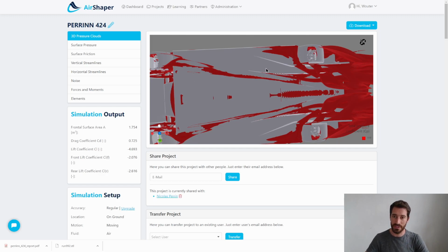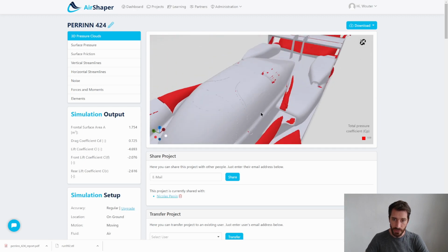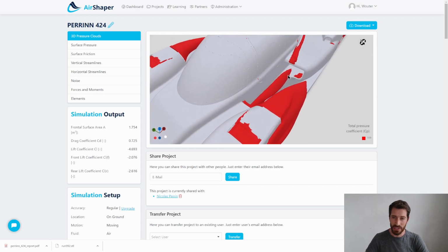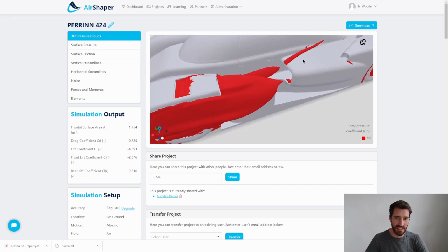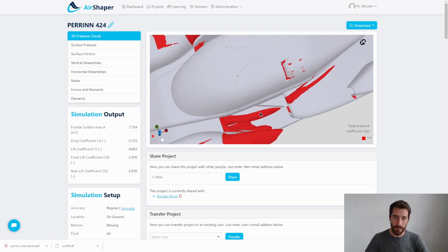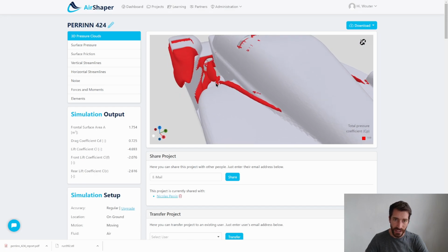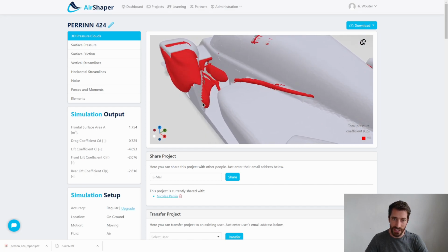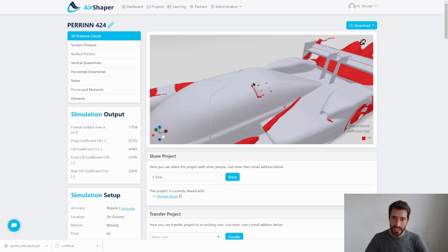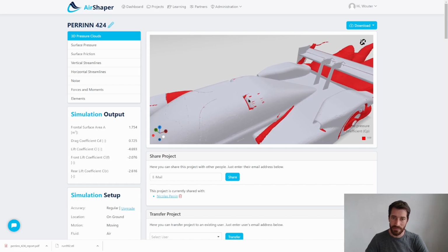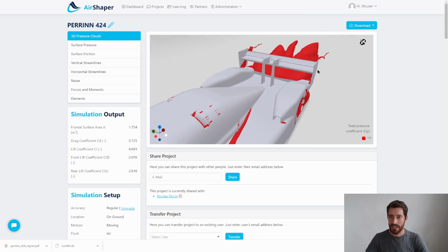to generate downforce. What you can also see is that in some areas, you'll still have flow separation, like there's a bit too much pressure here around the side inlets, so the air needs to jump up, and this creates a semi-separated vortex here. You can see flow separation here in the areas where the air needs to dive underneath the car and then needs to follow some negative curvature here behind the fenders on the front wheels. We can see that this outlet here of the cabin, slight bit of flow separation, but not much actually. The design of this car is actually quite good.